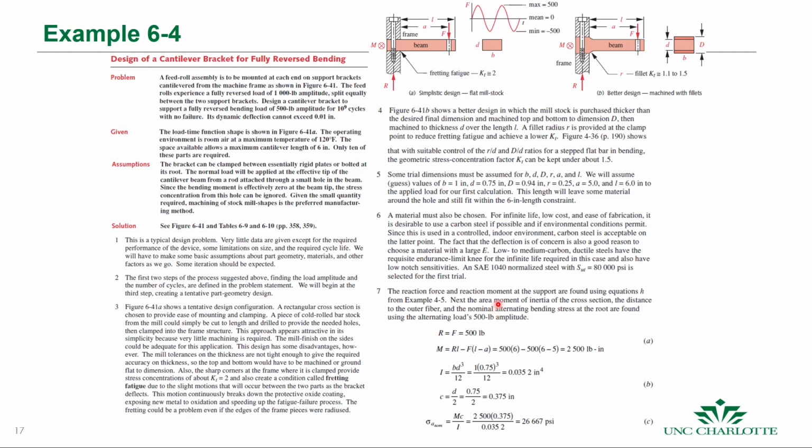Okay, and notice we needed to get our stress concentration, so we had to define some geometry first before we go in and calculate all the forces, because after we calculate them, we're going to have to adjust them for these stress concentrations, right? So here we just do static load analysis.